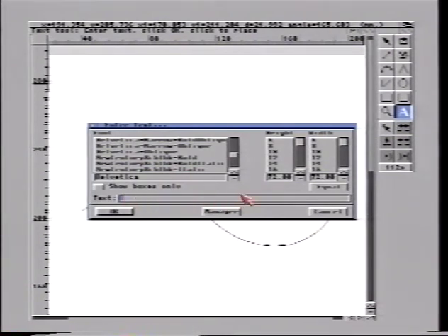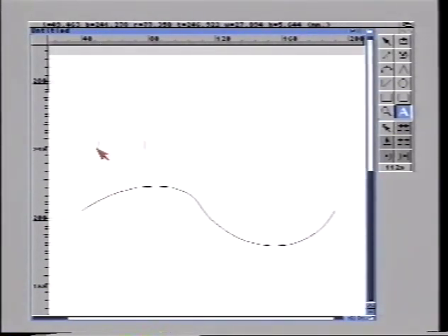The text will be entered as a string here. Choose a size and enter the text on the keyboard. Hit OK. The text now will appear as a blue box. There it is. I can resize it.